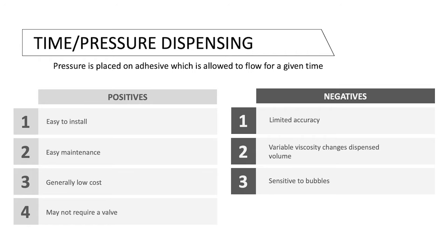They're also sensitive to bubbles in the syringes. So if you do have things like air trapped in the syringe from mixing, for example, that could lead to bubbles and bursts where you have small silver particles that are agglomerating in your needle tip and force you to change the pressure of the system, ultimately leading to misses in your dotting.